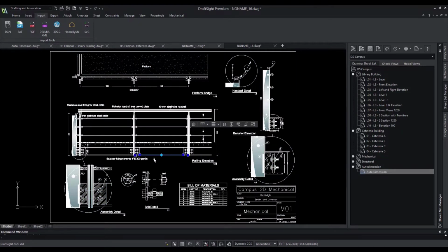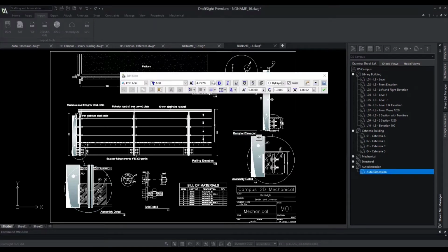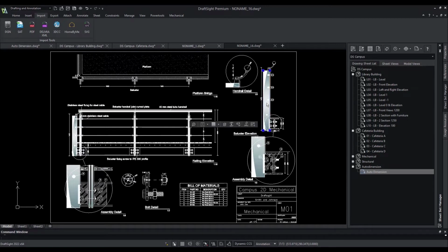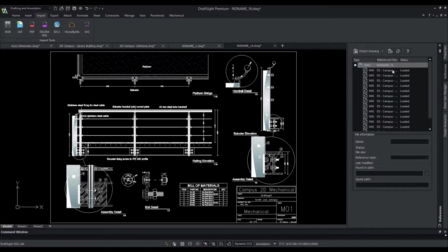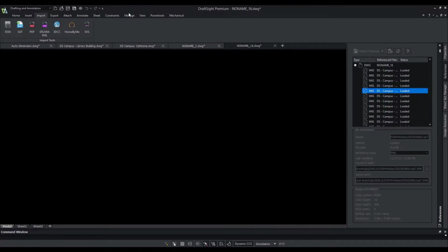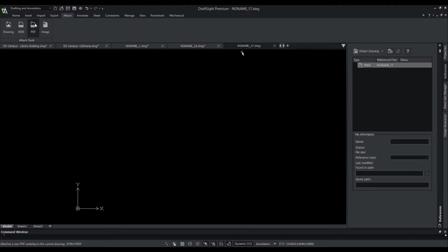vectors in the PDF files to drawing entities such as lines, circles, ellipses and splines, text lines in the PDF files to text entities using the fonts embedded in the PDF files provided on our computer, and raster graphics in the PDF files to image files on the hard disk. The images are referenced as images in the drawing where you import the PDF file.